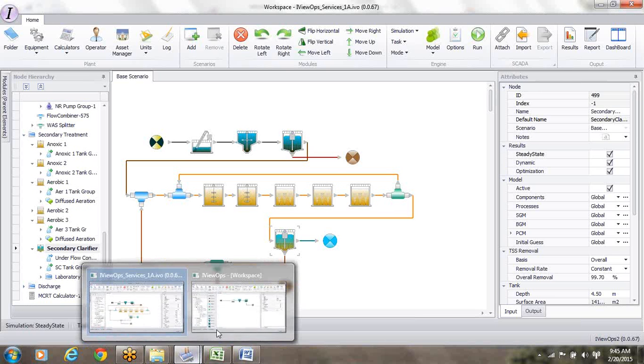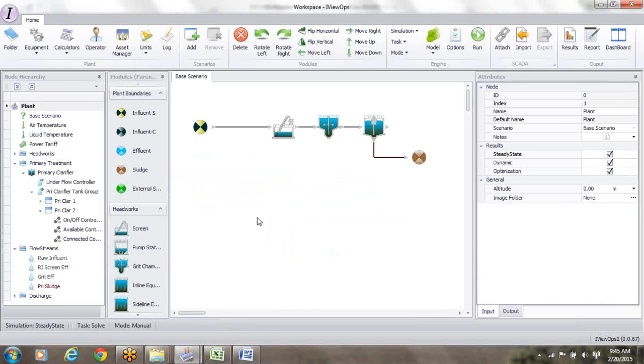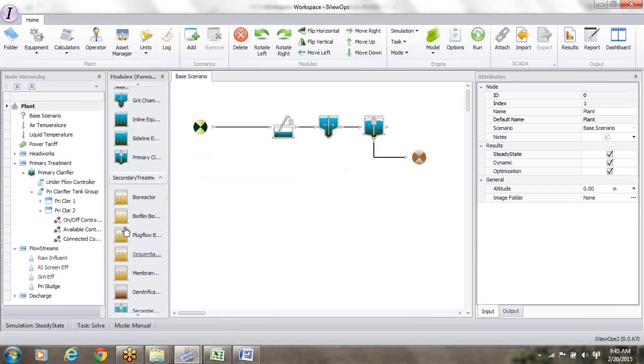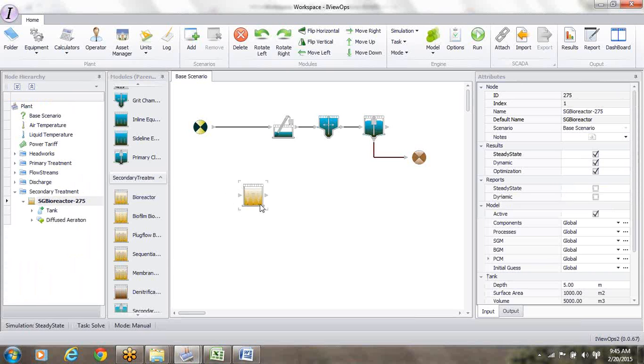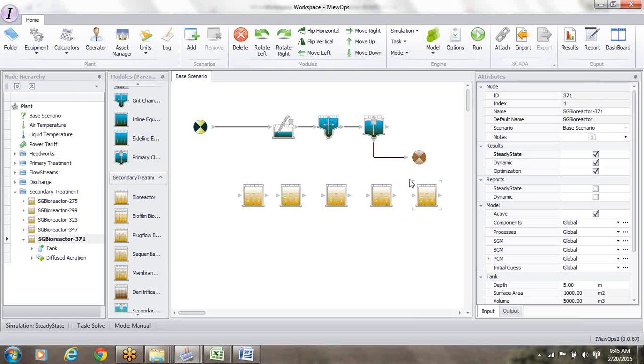So how do we go about building that? Now, if you think through, okay, I'm going to press the left mouse and I'm going to bring in a bioreactor here. Right now it shows as if the air is on. Okay, and I'll put it in for the second anoxic cell. I need another bioreactor. Then I said, okay, I made a decision to split the aerobic zone based on the diffuser drop legs into 3. Okay, so here are the 3.